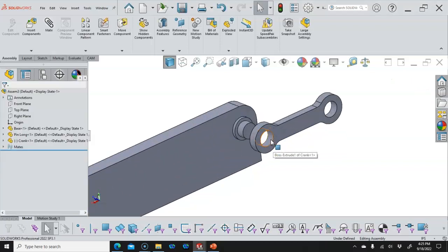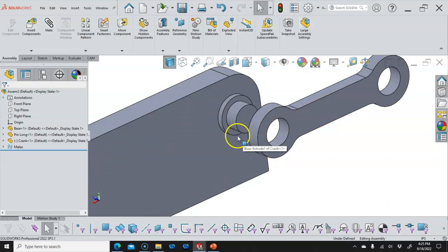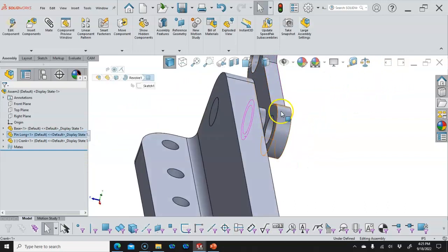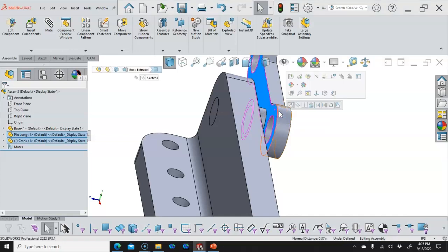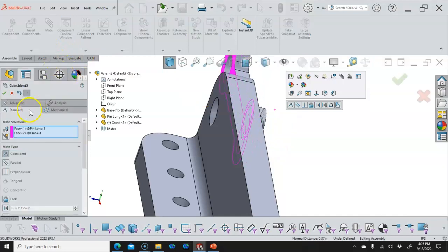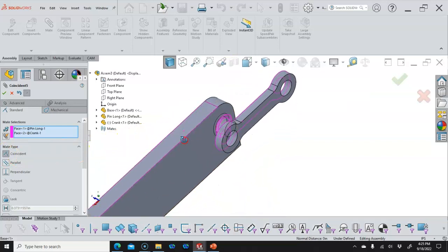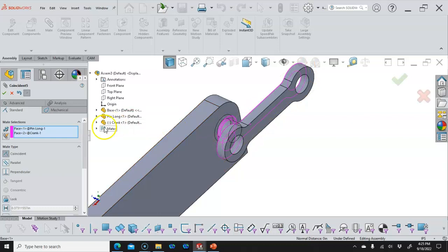And then I can do the same kind of thing here where I go coincident. So select and control select is still going to be faster because you're going to get that pop-up. Initially, if you go up to the paper clip and you've pre-selected, it's going to jump to coincident, or if it's one of our cylinders, then it's going to jump to concentric. So to start off with, we're going to be using those two mates quite a bit.